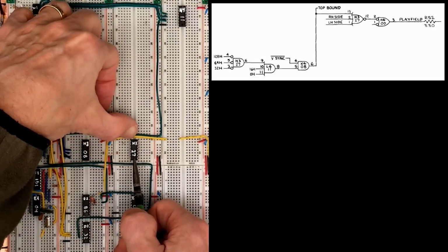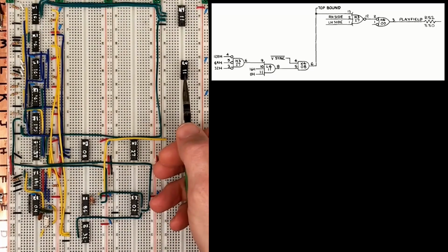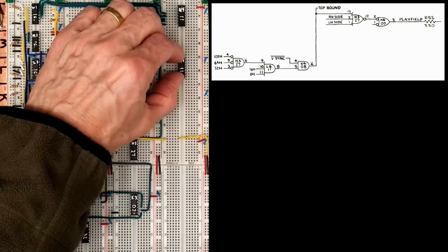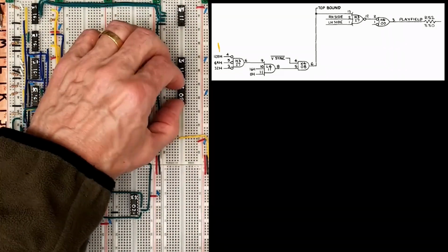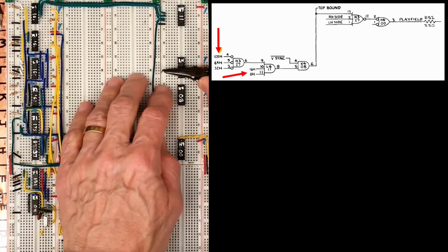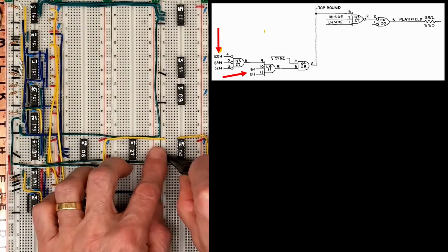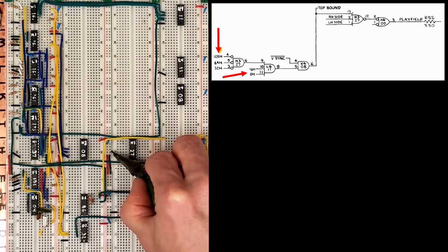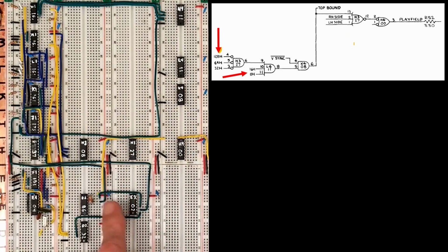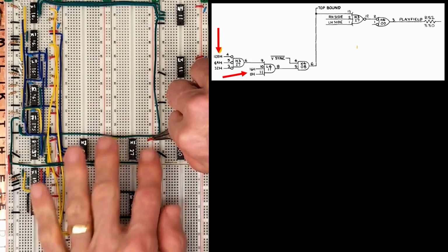Let's drop in the additional parts needed to generate the borders. We'll start with just the top boundary. These signals here are the non-prime versions coming off the flip screen logic, so we'll just use the prime versions today because we still need to add that flip stuff. I'm going to use temporary jumpers for any counter lines then.